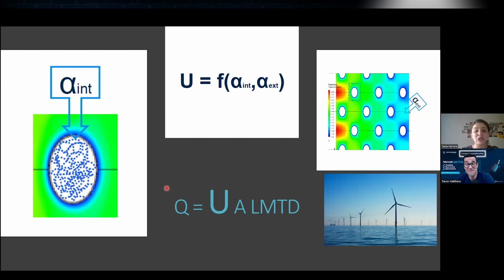Yeah. But also, if we're talking about evaporators, if they are coolers, this means that we will have water, because there is humidity in the air, and your coil will be cold, right? Because you are cooling something. And when the air touches this colder temperature, the humidity in the air will condense, and we will have water droplets within our heat exchanger.